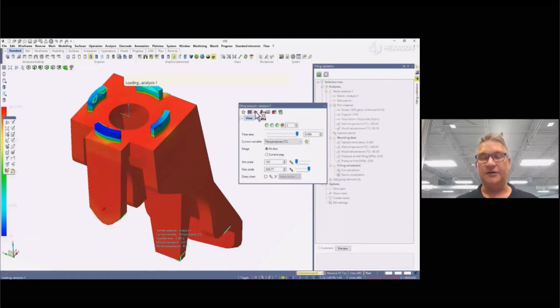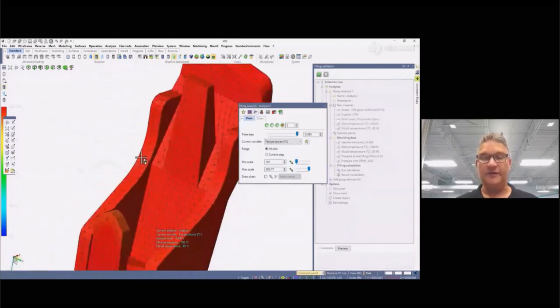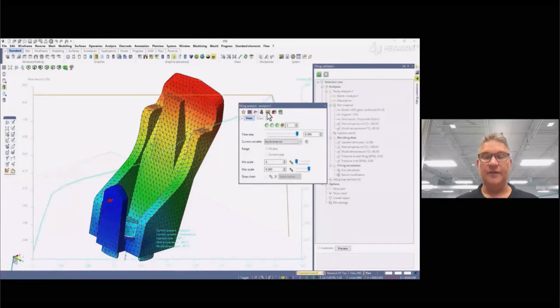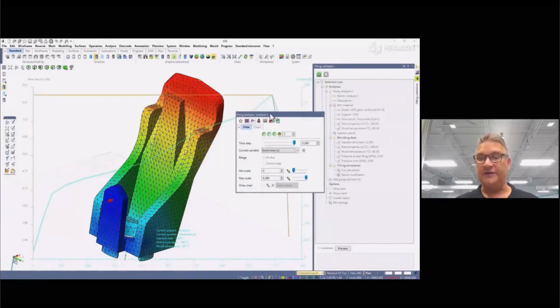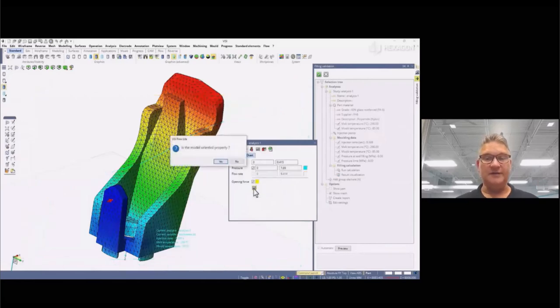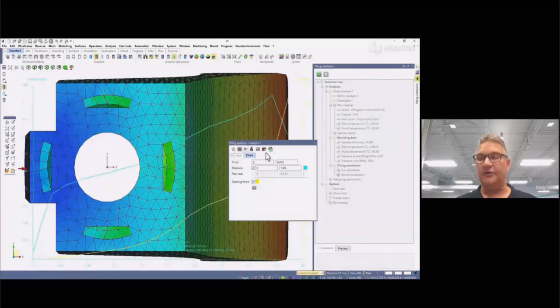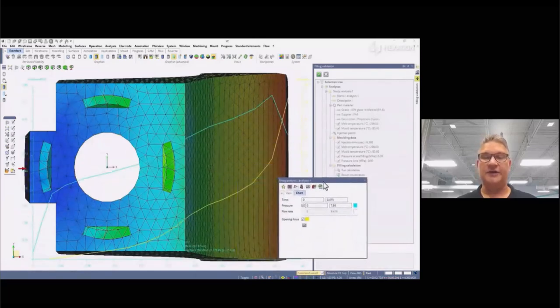Now run a calculation to show air traps and weld lines, which are displayed on the model. This helps for some design decisions. Click to display the graph chart, then show the filling with pressure. Properly orientate the model, orientate the part to the mold position to calculate the clamping force needed for this part.